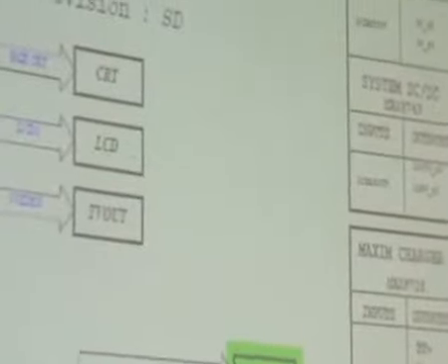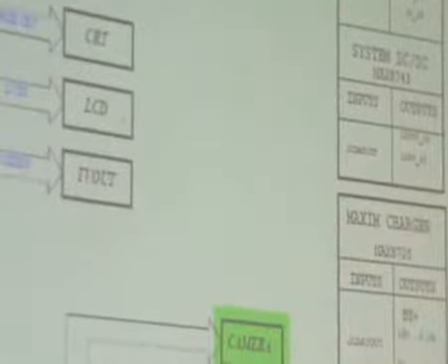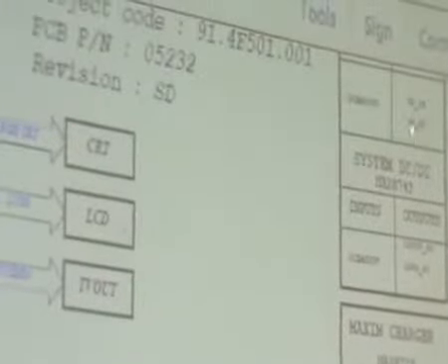Like 1D05S0, wherever 1D05S0 is written, it is coming from this MAX8743. Then you have the 5 volt, 3.3 volt regulator IC. This is 5 volt S5, 3V S5. So this is the 5 volt, 3.3 volt regulator IC. We will discuss this power section in a later session. In this class we are discussing the CPU supply. So we will move on to pages 4 and 5.